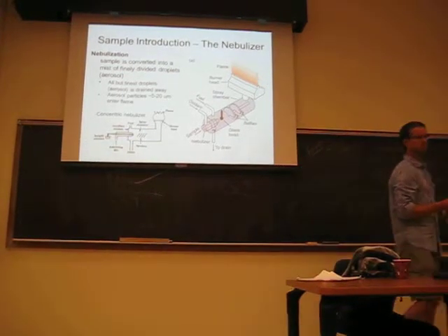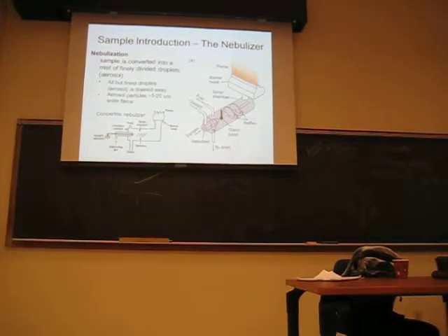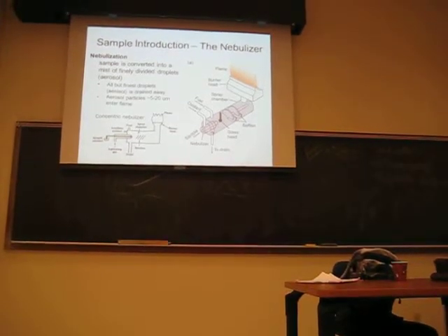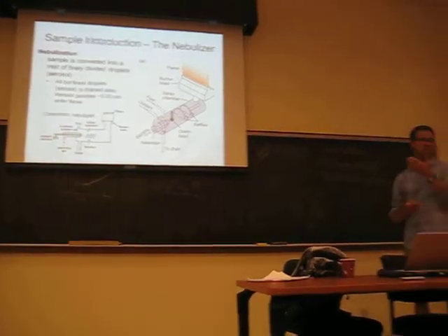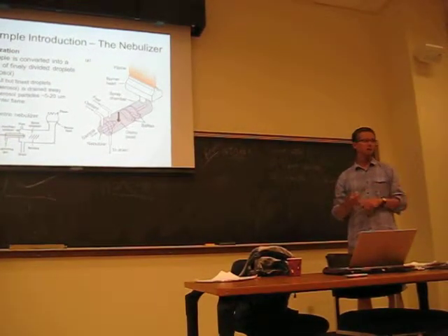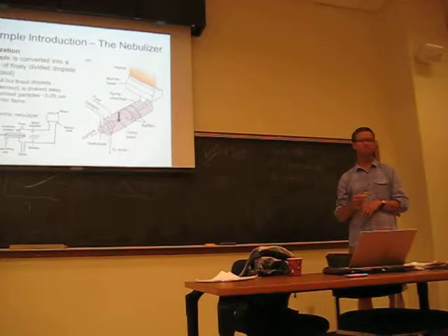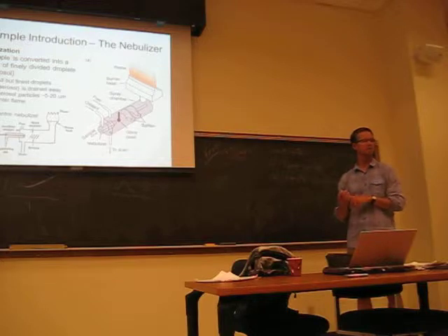How much sample do you actually enter in the? You'll find out. So typically, if it's aspirating at maybe a couple mils a minute, depending on how you set it, then you would probably want to start with at least 5 mils, and if you need to remeasure it because it didn't look right, usually you want to come in with something like 10 mils of sample.